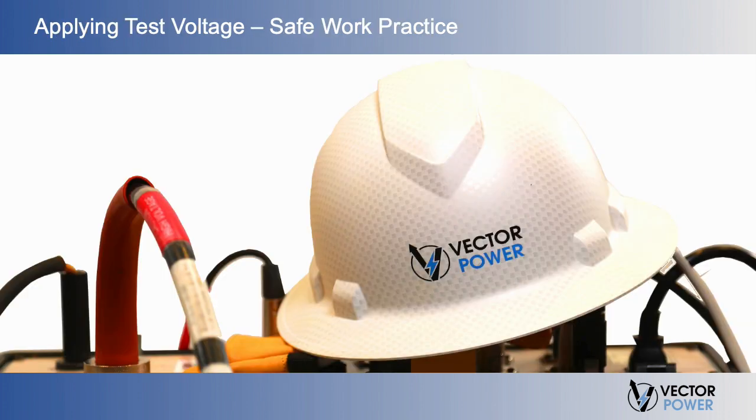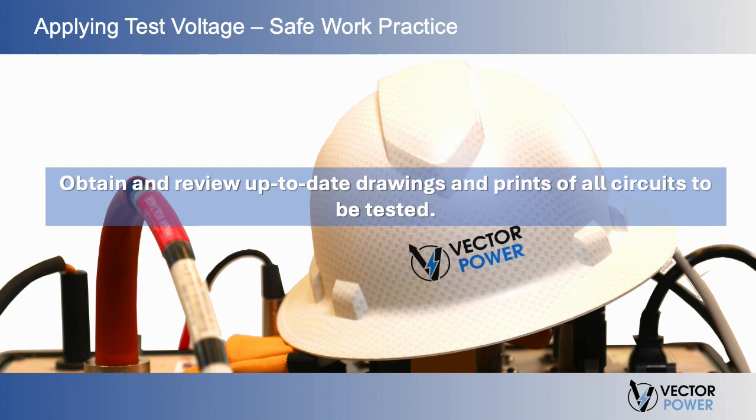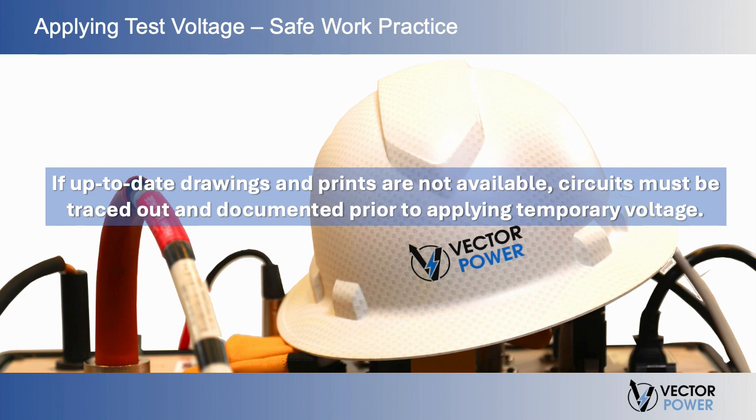Let's review some safe work practices whenever we are applying test voltages. Obtain and review up-to-date drawings and prints of all circuits to be tested. If up-to-date drawings and prints are not available, circuits must be traced out and documented prior to applying temporary voltages.